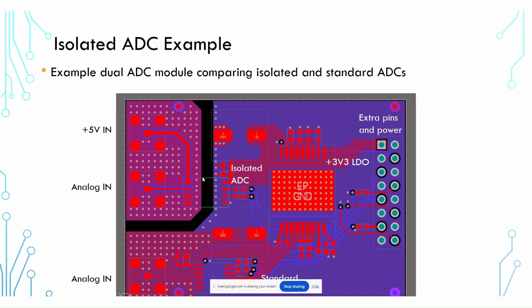Now, here, this is very important because what I'm doing is showing all layers in this Altium Designer project. I've dimmed the polygons just a little bit so it's very clear, and you can see that we are looking at multiple layers. You can actually see the traces on the back layer going up to this pin header. But what you can see here when we have all the layers turned on is that we have a gap between these grounds that spans all the way through this section of the PCB.